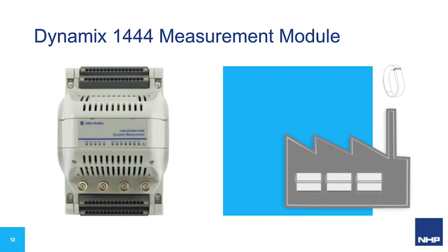So I'll talk about the dynamics measurement 4-channel module, which you can see over here, and you can see this as the Fitbit for our integrated condition monitoring. This device is simply connected to our existing control system like any standard remote I/O would be. But this module is actually crunching the numbers. Essentially, it's converting the raw time waveform that we saw earlier to the spectrum for evaluation of those various frequency windows.